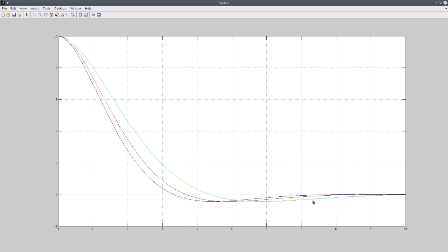If you have an actuator and you know that you should not exceed certain limits with your actuator, you cannot arbitrarily choose your pole locations. You need to be aware what's going to be the effort that will be exerted on the actuators. And so LQR optimizes that for you while trying to balance a good response in terms of the state vector, as well as having bounded or let's say desirably bounded control variables with respect to time.